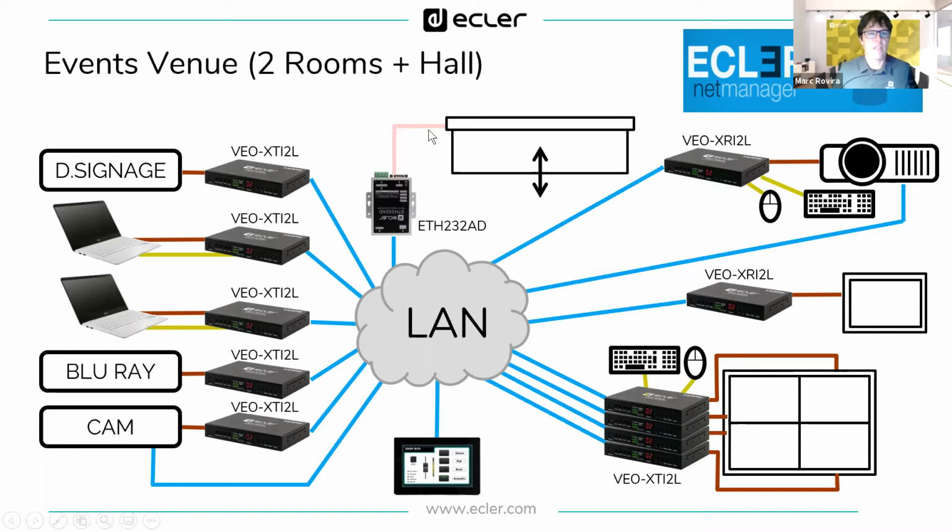Okay. In the same way, we have got an RS-232 converter to connect anything that works in RS-232. This device has a LAN connection, so a network connection, and translates the messages that arrive here into RS-232 for controlling, for example, a screen that accepts RS-232 messages. So you will be able also in this way to control the screen.